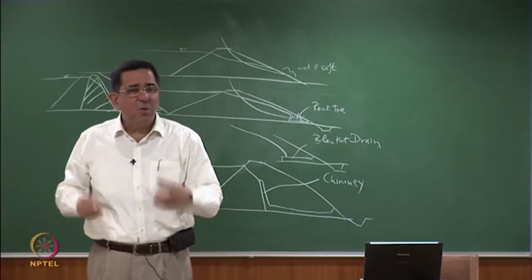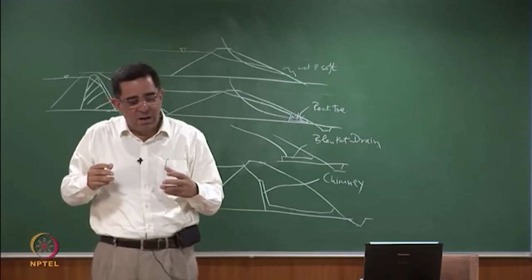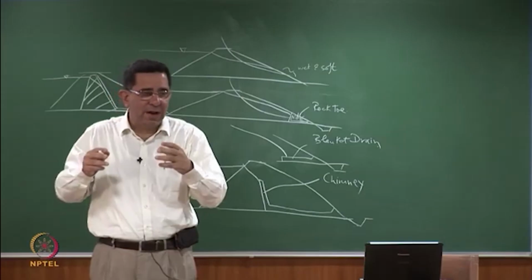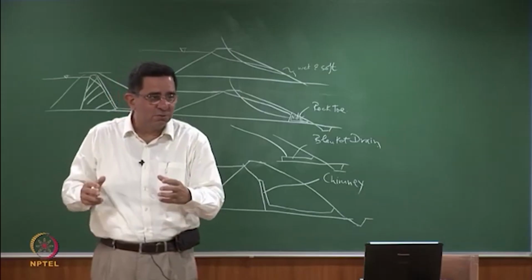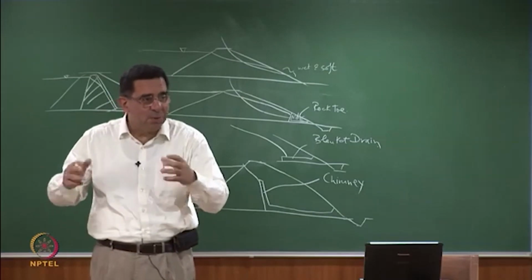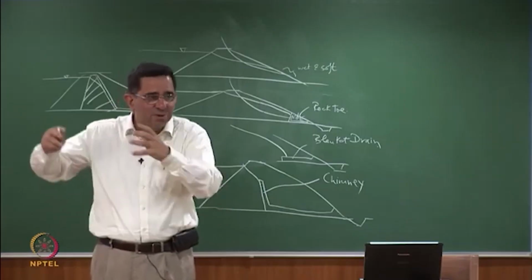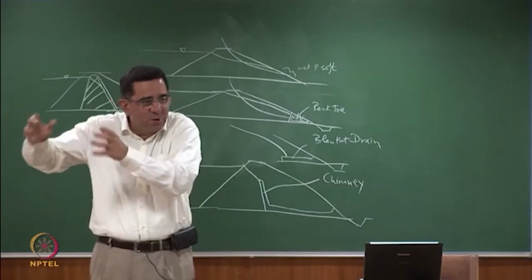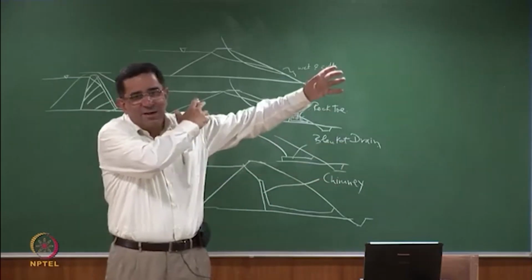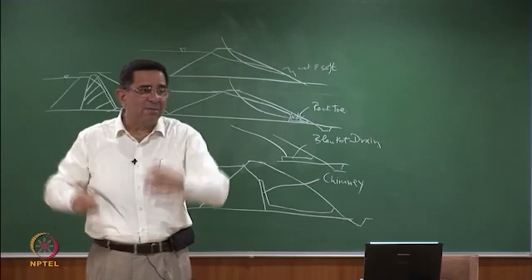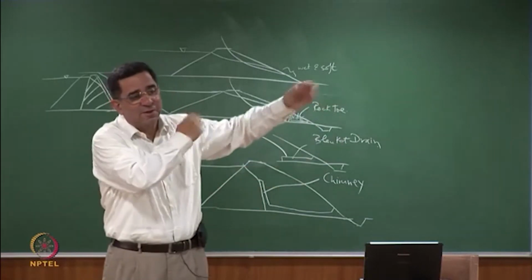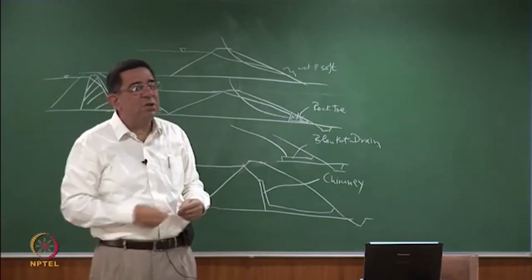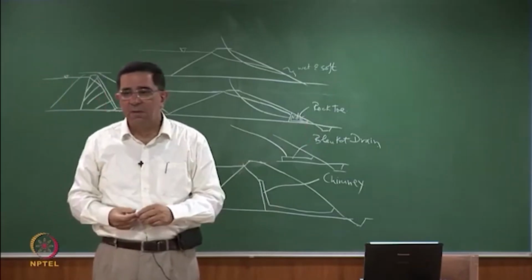But believe me, once the embankment of an ash pond or a tailing pond begins to move, it begins to move in a big way, and the slurry comes out like water. It's not a small failure. It may move down several hundred meters, and tailings dams have moved 2 kilometers. The slurry has gone out like water. So there's a breach in the embankment, as you may say.